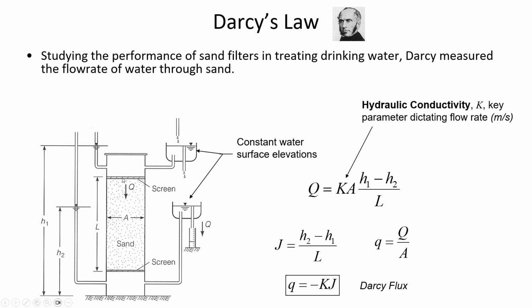But water pressure increases as you go down through a fluid, even if it's a fluid in between soil grains. So the pressure is increasing as you go down through the fluid, but the reason why the liquid level rises to less of a height at location 2 is because of the energy loss as the water travels through there. So the difference in the water elevation isn't because of the elevation difference, it's because of the energy difference.